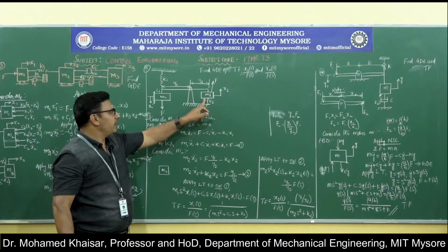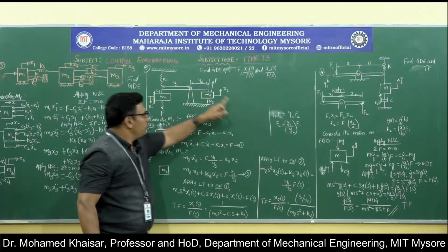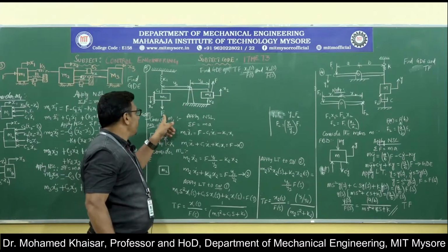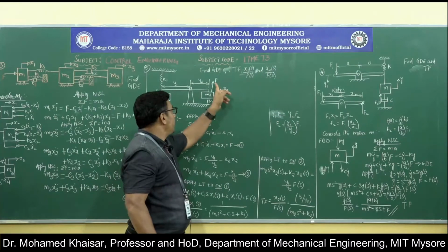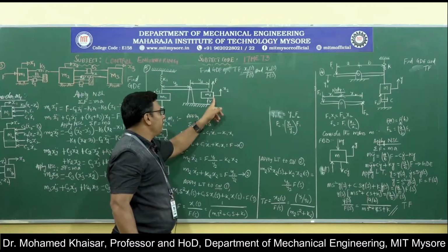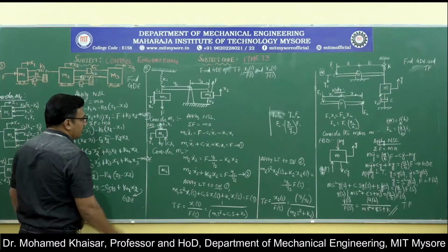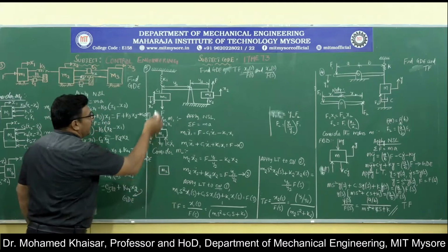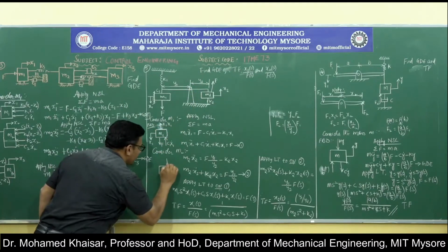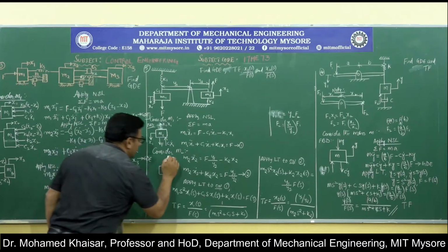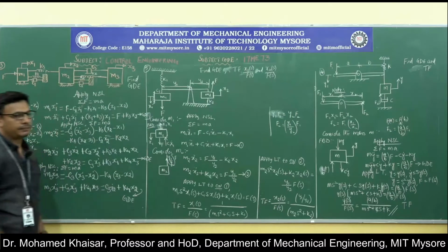The force experienced by mass m2 will be equal to F into y1 is equal to F into y2. We name it as, say, if this is F1 and this as F2, y1 F1 is equal to y2 F2, and if we try to find what is the force experienced by the mass m2 over here, it will be equal to y1 by y2 into F1. So, the disturbing force over here, if it is in the downward direction, here it will be in the upward direction because of the leverage mechanism. So, F, the disturbing force will be equal to y1 by y2 into F.